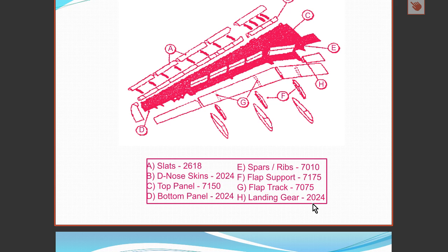One thing that's not stated here is that for surfaces that are exposed to the elements, they must be coated with a pure aluminum layer to prevent corrosion. We will learn later on that the precipitates within the aluminum increase the chances of corrosion in a material due to the differences in composition. And so these materials must be protected against the elements by a layer of pure aluminum that is bonded on top of them, if they are going to be exposed to the elements.